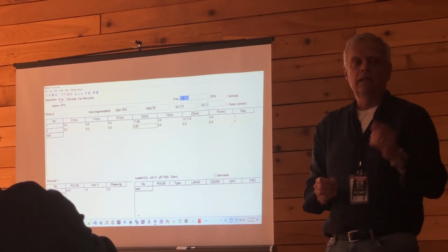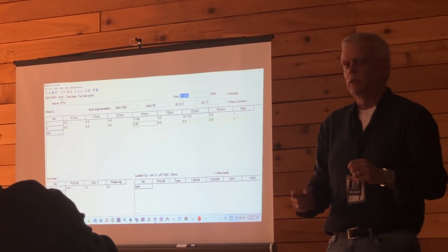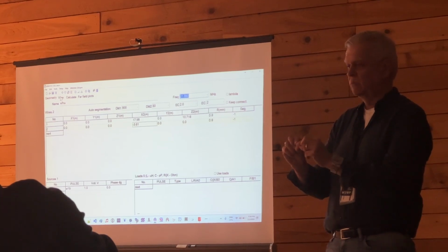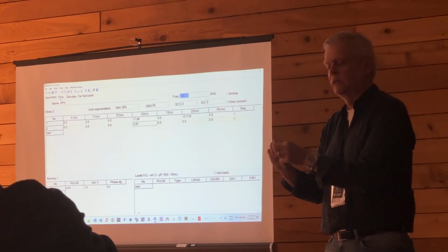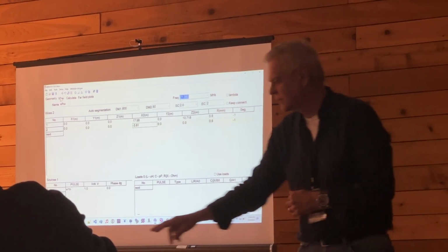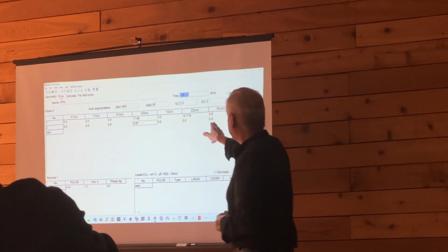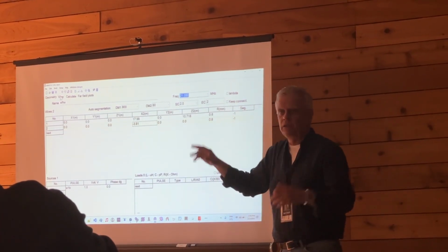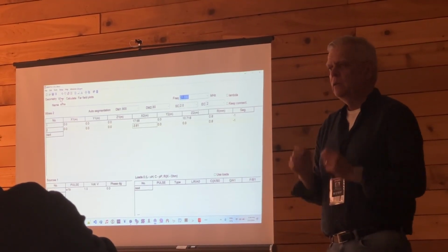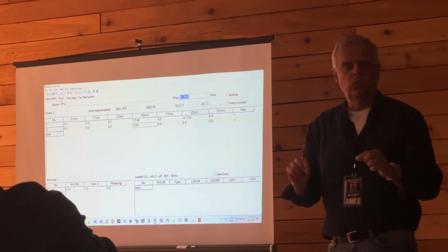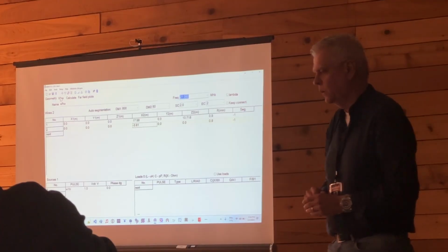I don't know. And the other thing is we're glossing over a lot of points here. For example, a gentleman might be using a very large gauge wire or a very thin gauge wire. The program gives us the capability to enter the gauge of the wire here. We didn't tweak it, assuming 0.8 millimeter wire, whatever that AWG gauge comes out to be. But these things can change depending on gauge of wire, and obviously the frequency that we're going to try out.